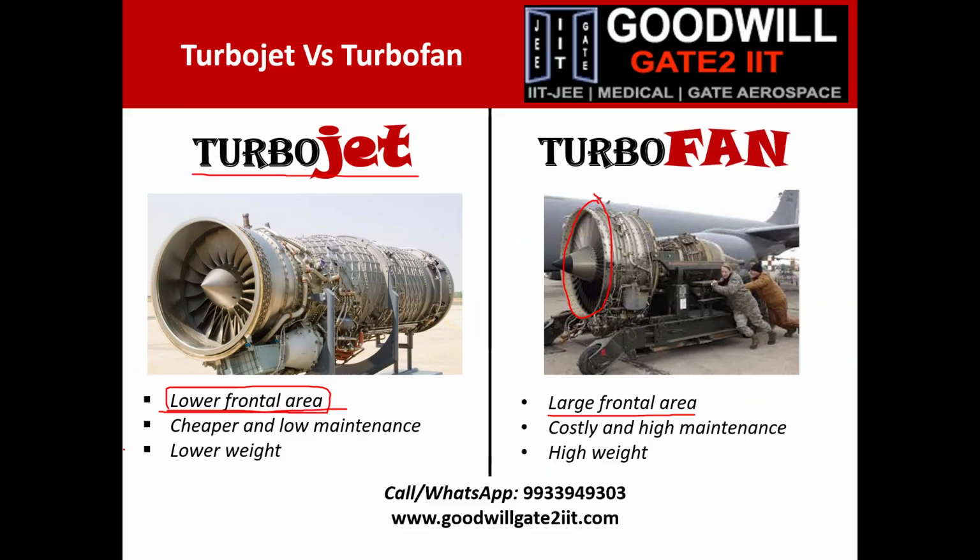Second, because you have less complicated parts, turbojet engines are cheaper and very easy to maintain. Whereas turbofan engines are costlier. You need to make big fan blades, big arrangements, and bigger engines, and hence it requires high maintenance also. This is the reason your turbojet engines are lower in weight and your turbofan engines are higher in weight.